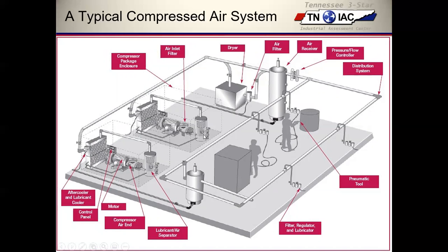There's an element in here. Oil falls down to the bottom. It goes back over here to the heat exchanger to get cooled off, and then goes back into the compressor. We have our compressed air coming out of here. It's hot, hopefully mostly oil-free. Goes through the other part of the heat exchanger and then comes out to the system. We're showing the supply line.